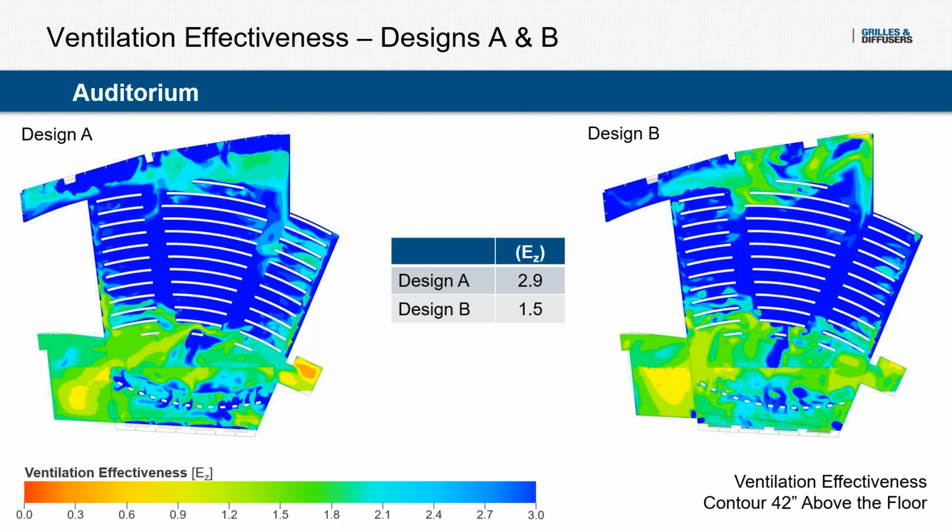And actually, in both cases, the ventilation effectiveness is still higher than what you would see in the tables in standard 62.1. 62.1, as you know, stipulates that displacement is about 1.2. So even in the worst case, in air quotes, you're still getting a ventilation effectiveness of 1.5.